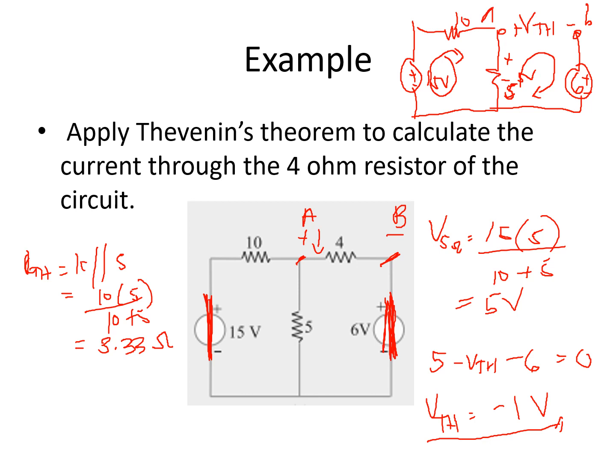So the circuit here now is negative, positive, okay? So the terminals or the polarity is like this, 1 volt. It is in series with our RTH. This is 3.33, and this is terminal A, and this is terminal B. B is positive because we got the negative sign there. So it should be minus plus and not plus minus.